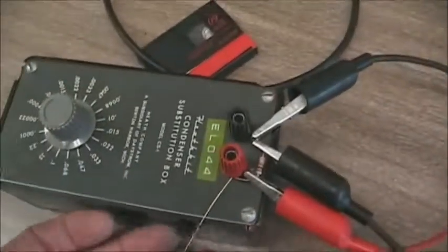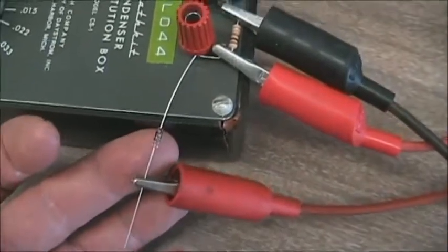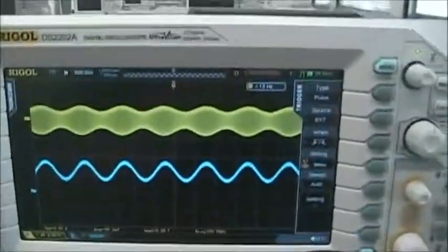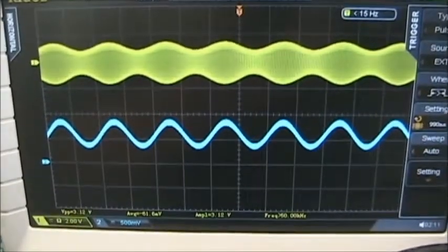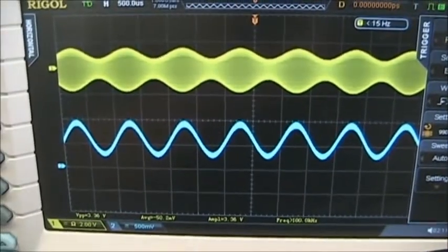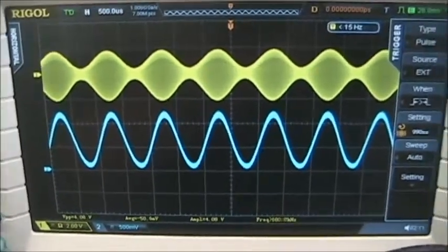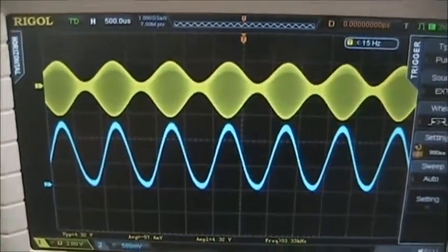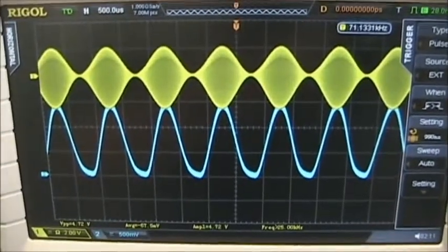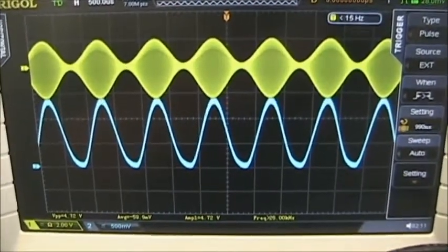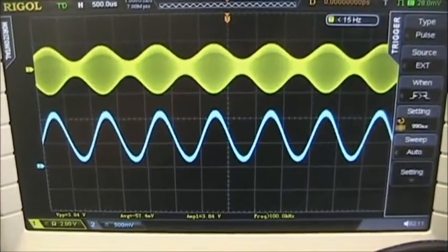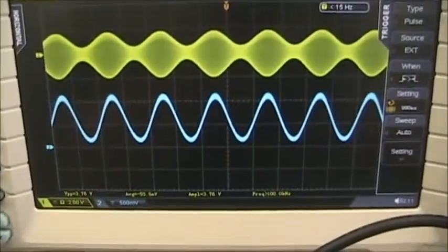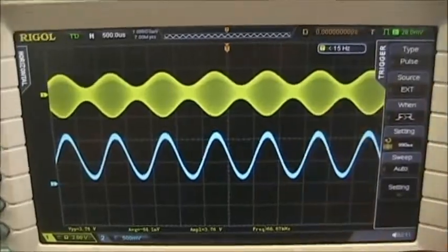Now I've changed the diode to be a germanium diode. Now remember, germanium diodes have a forward voltage of only 0.2 volts. The value of being able to use a germanium diode is if I increase the modulation index, I can go to a much larger value because it takes minimal voltage to turn on the diode. So now that's 100% modulation, but we get a good looking sine wave even at 70-60% of modulation. So the diode and the capacitor all determine the aspect of the demodulated signal.